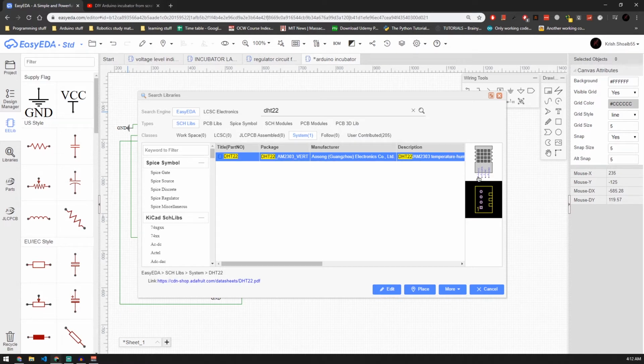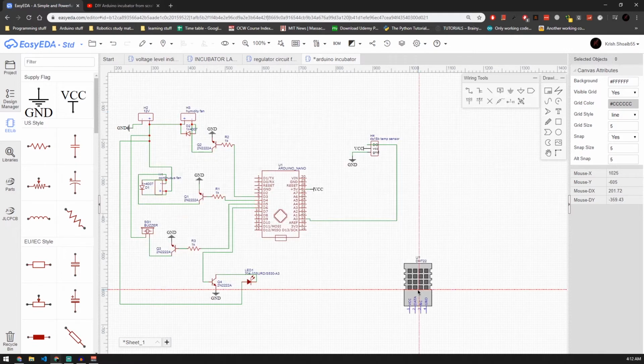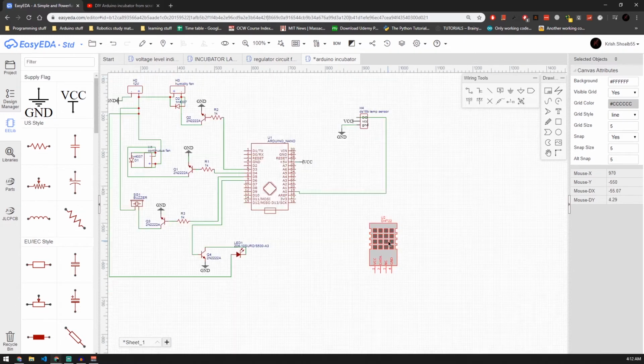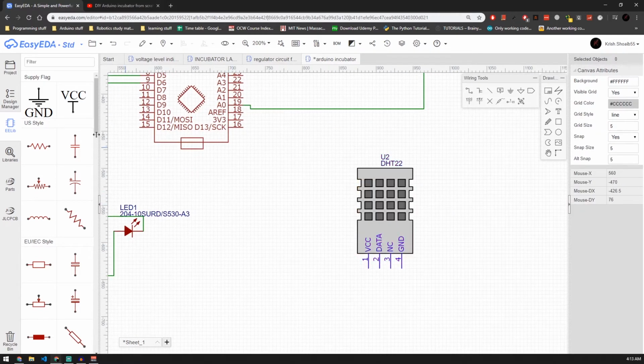Yes, oh, that's a pretty nice graphic right there. So this is gonna serve as a correction point, or a comparator, maybe, as it's called. It's gonna compare these two values. So if one of them fails, the other one should be there to protect our circuit, and we could get a warning that our temperature sensor has failed, because these things really do fail, and when these fail, everything is gone. Let's connect our ground here and connect this.